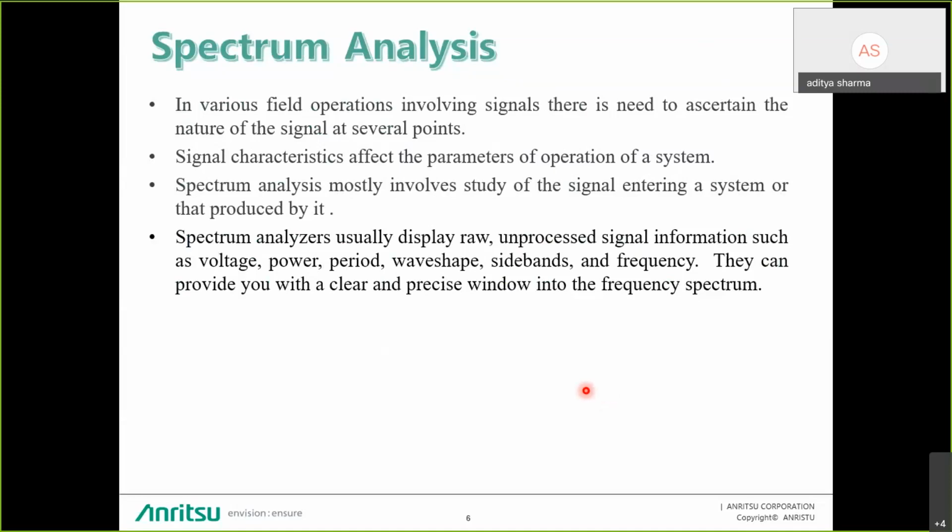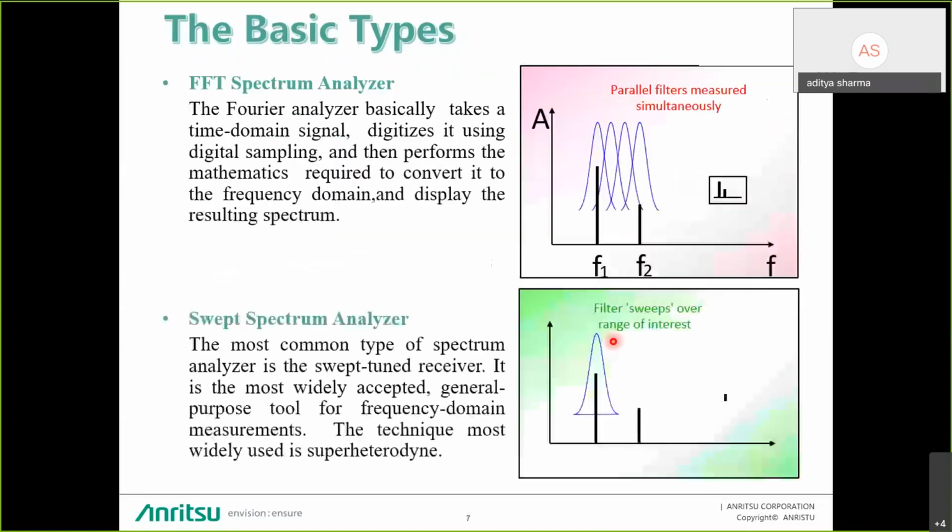Yeah. So like I told you, there are two basic types of spectrum analyzer. One is the FFT, fast Fourier transform based spectrum analyzer. Then we have the swept spectrum analyzer. So in the FFT spectrum analyzer, what happens is that the time domain signal is digitized, which is digitally